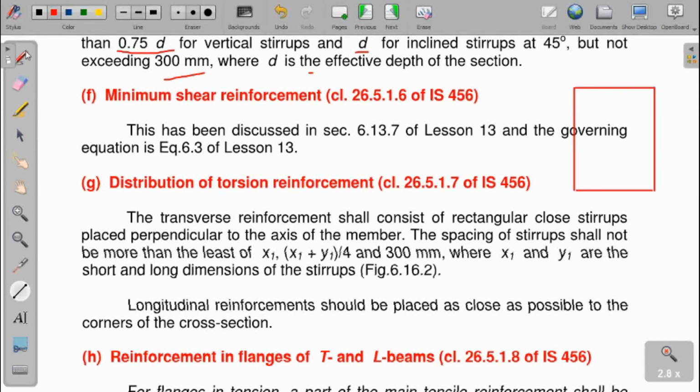So what I have to do, I have to place some reinforcement here. These are the main reinforcement I am providing here. It is a round shape basically. Main reinforcement is to be provided in a round shape. So these are the main reinforcement I have provided. So from the center of the main reinforcement to the center of the main reinforcement here, this is called y1. This is denoted by y1.